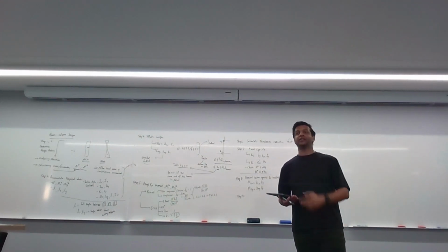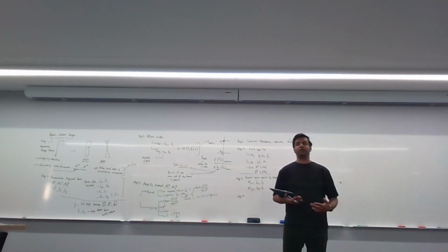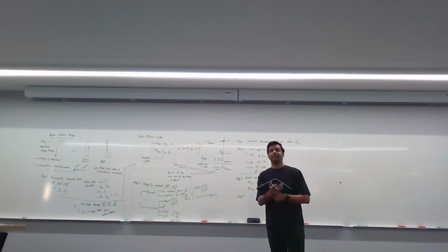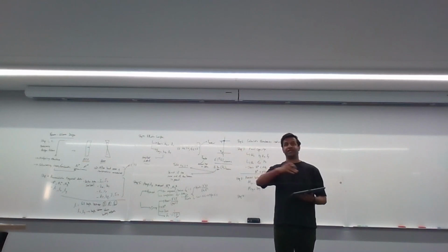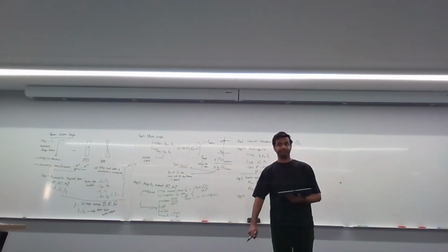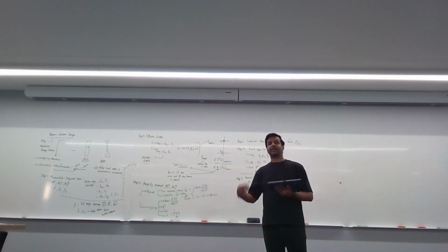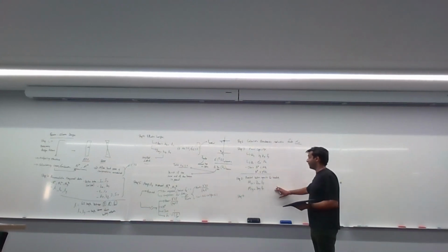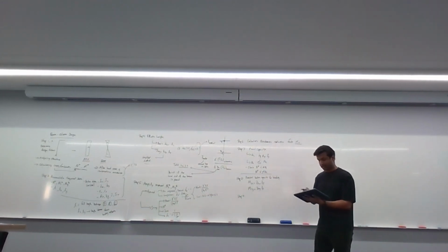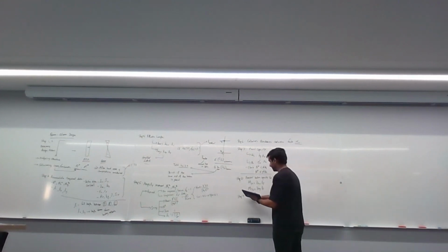There's a line or two of formulas in the code that you've got to calculate, and if it clears that clause, then you take it as continuously laterally restrained. If it doesn't clear it, then it's not continuously laterally restrained, and you need to find the member capacity.